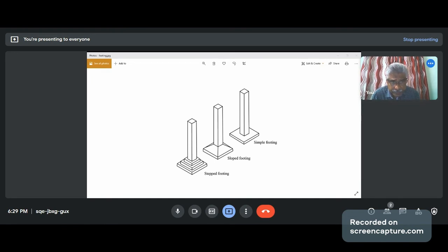So, in the design of concrete structures class, the isolated footing is designed by knowing the bearing capacity. This will be known to you. Based on the bearing capacity, we need to identify the plan dimension of the footing, because some P kilonewton will be acting on the column, which you may get from structural analysis. You must be familiar with structural analysis of simple portal frames and all.